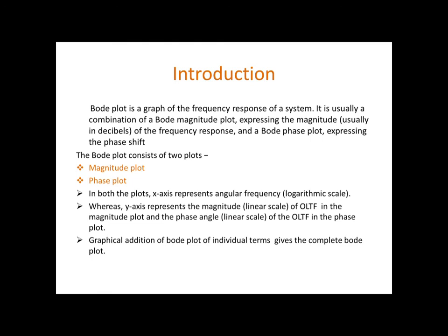So, to avoid this, it is convenient to plot the magnitude and the phase shift curves with a logarithmic scale. And this plotting of magnitude and phase shift with a logarithmic scale is known as the Bode plot.